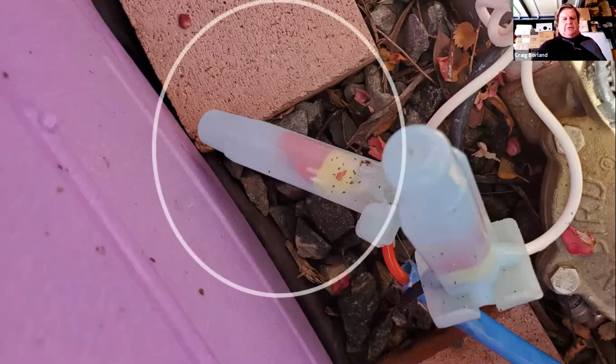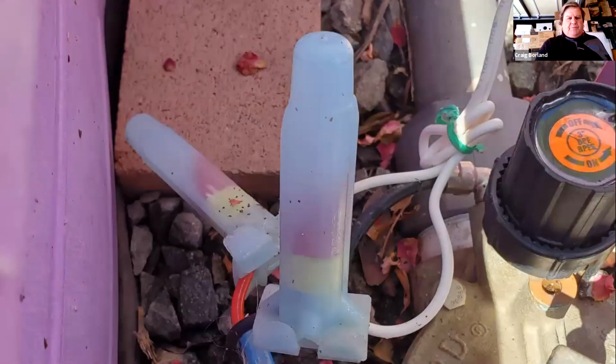Look in this photograph. Where's the wire nut inside the tube? Barely inside. The one to the right's even worse. When you use these things, the wire nut has to be all the way to the bottom to provide the best moisture protection. Why are we worried about moisture protection? Because the 2-wire path in many cases is 24/7, 365. It's on all the time.